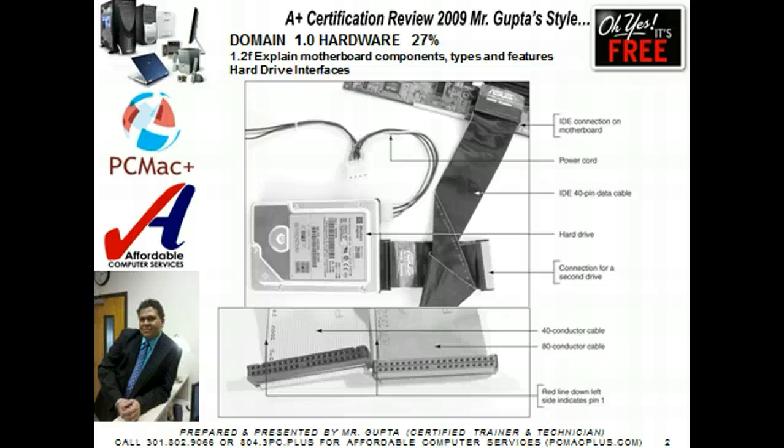These ribbon cables can accommodate 1 or 2 drives. All PATA standards since ATA-2 support this configuration. Using this standard, up to 4 parallel ATA devices can connect to a motherboard using 2 data cables.